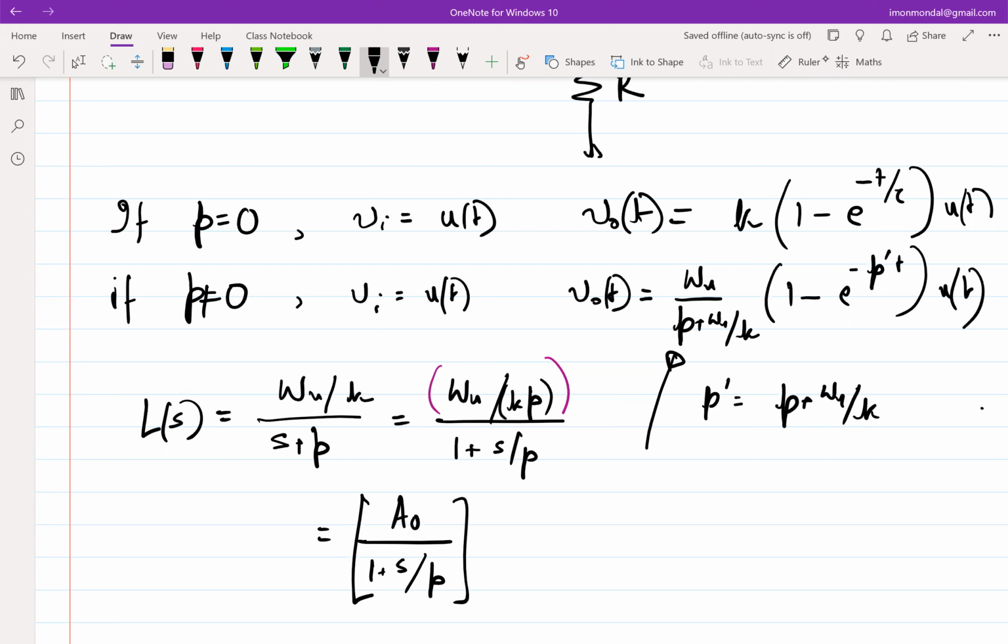So as you see, it is quite natural to obsess over where the unity gain frequency of your open loop feedback system is. Because if you are designing negative feedback to make sure that the closed loop system works as you want, you would also like to know till what frequency your closed loop system will work properly. And that frequency happens to be the unity gain bandwidth of the loop.